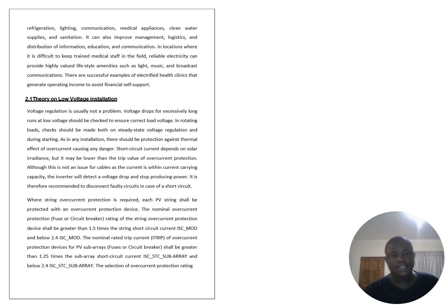Although this is not an issue for the cable as the current is within the current carrying capacity, the inverter will detect the voltage drop and stop producing power. It is therefore recommended to disconnect a faulty circuit in case of short circuit. While a string overcurrent protection is required, each PV string shall be protected with overcurrent protection devices.